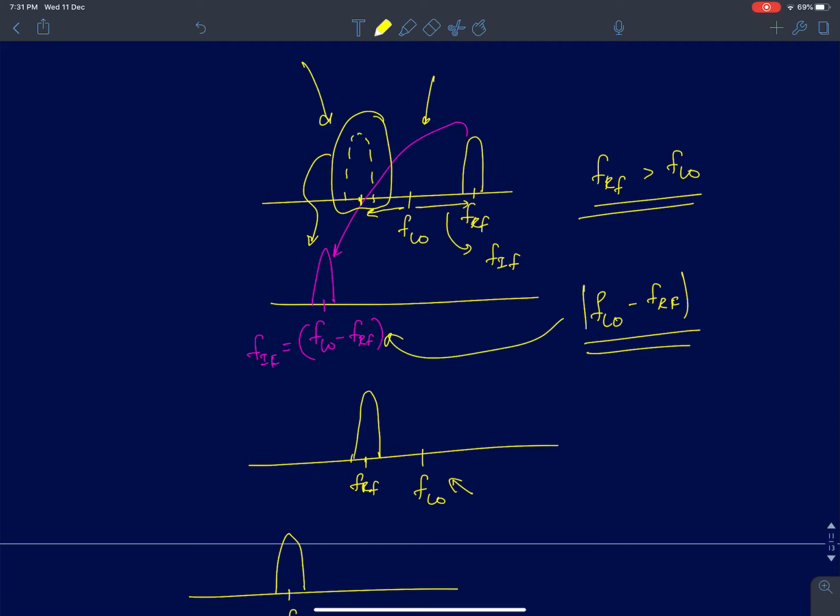Now the image frequency is a major issue in heterodyne receivers. So we need to introduce an additional block called the image reject filter. We need a filter which can reject the images. That filter is called the image reject filter, IRF. There is a term called image rejection ratio. After you pass the signal through the filter to the receiver, you will see how much the image gets rejected. So we will have to define IRR, image reject ratio, when you go for heterodyne receivers. So that's one of the main problems. It comes with other problems, but I just discussed this main problem for heterodyne receivers.